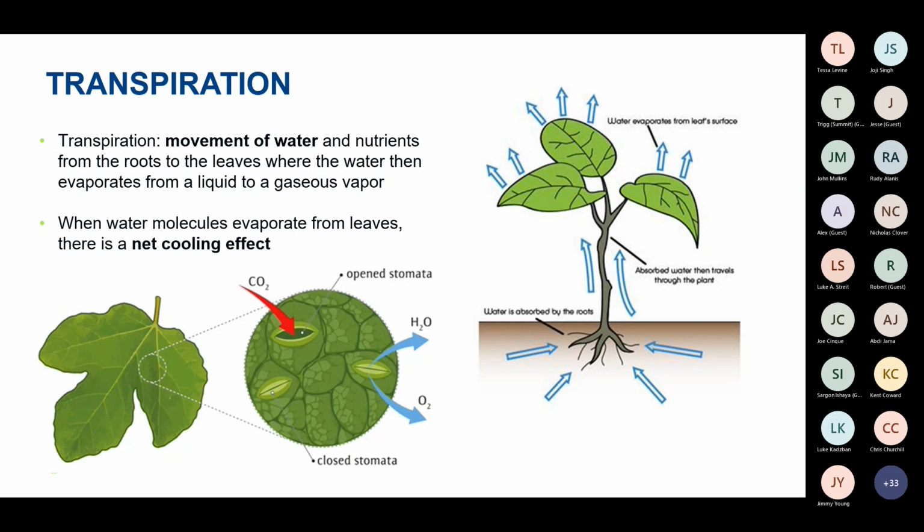So therefore, transpiration is the primary source of humidity being generated in a sealed grow room that a mechanical system must remove by dehumidification. And transpiration and photosynthesis are separate processes, but are intrinsically linked since they are both regulated by the opening and closing of the stomata, which are little pores found on the underside of the leaves that have the ability to open or close depending on the environment and are where all the gas exchange occurs. So CO2 enters while oxygen and water vapor escape.